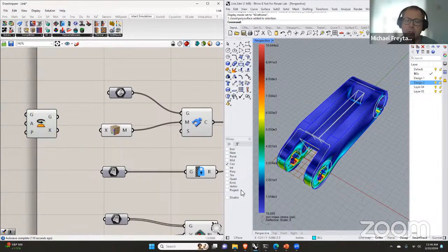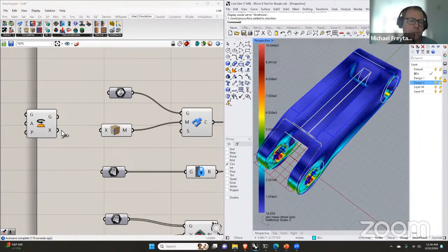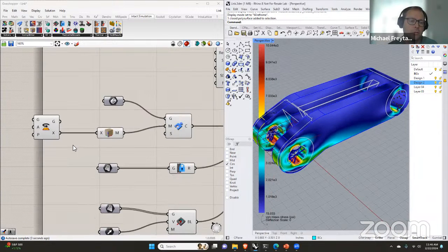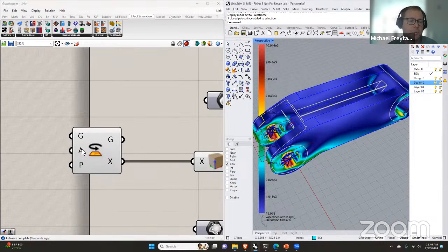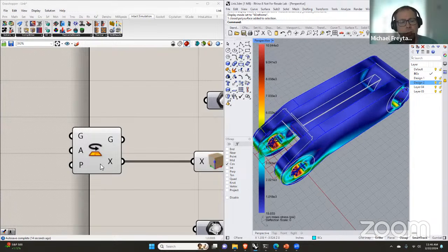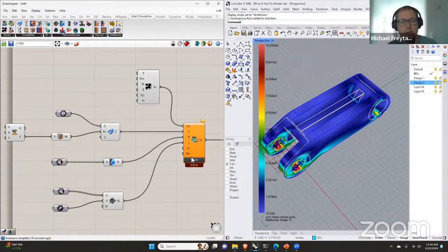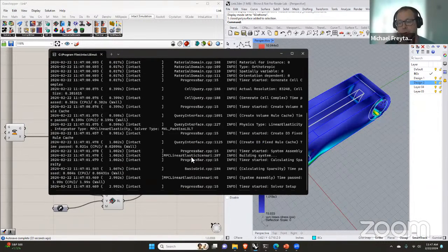If I display that, I think the local x-axis of this transformation is pointing along the axis, so I can plug that in here. It's probably correct, because I'm rotating 90 degrees from X this way into this, in the XY plane. So that material is set up, and I can hit solve.